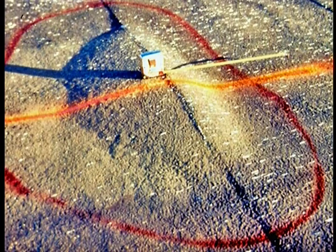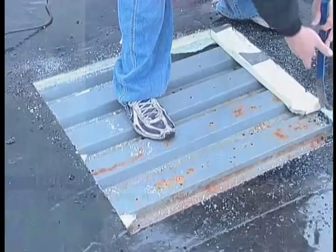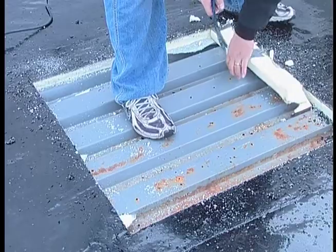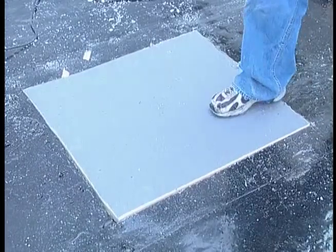If the existing system remains, cut down all blisters and secure with screws and plates to make a level roof surface. If water is present, remove it along with wet insulation. With insulation, build up the resulting voids to the surrounding surface level. Apply the appropriate underlayment material and separator, then install the roof as required.